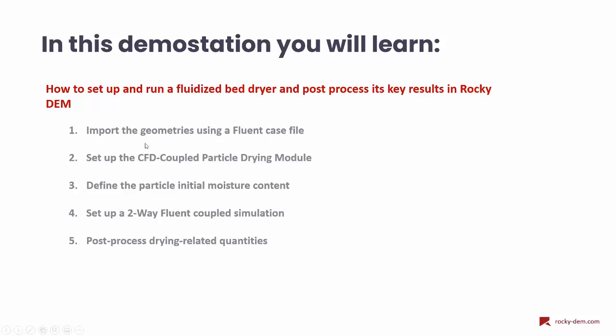Also, we will learn how to set up the CFD coupled particle drying module, which is the module that will allow us to consider the drying process caused by a fluid flow. We will also learn how to define the particle initial moisture content, and also how to set up a Fluent two-way coupled simulation, and then post-process the drying related quantities.